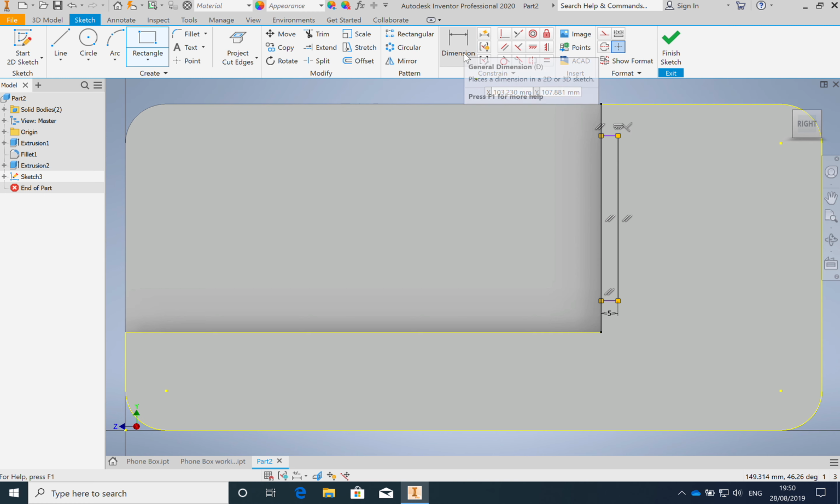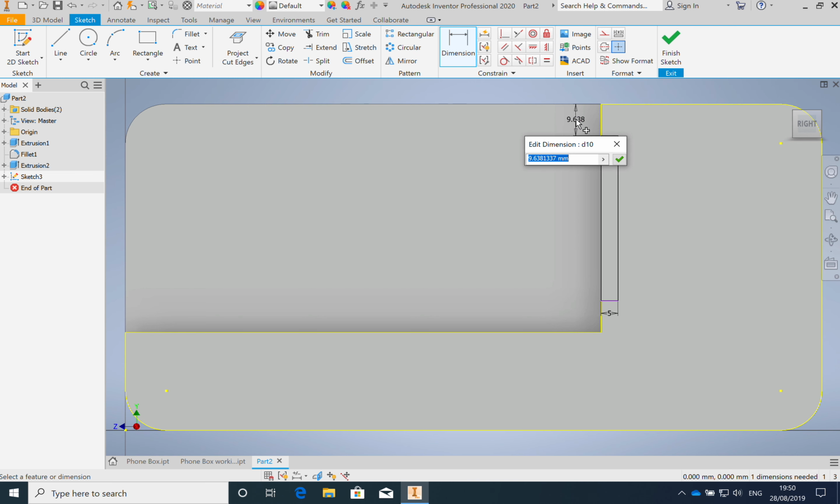You're going to define that second dimension by creating dimensions from the edge. So I want you to click this button and then click on this line. It thinks you are dimensioning that line. Don't click again. I want you to then come down and click on this line here. And now you can see that you're dimensioning between this line and this line. Click one more time on the outside, so that's 3 clicks to do the whole thing, and then tap in 10, like that. You're going to click again, you click on this line here. It thinks you're doing that until you click on the bottom of a rectangle you've just clicked on, and then click on the outside there and tap in 10 millimeters. That's now giving you a nice square here.